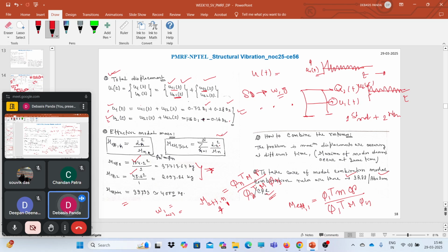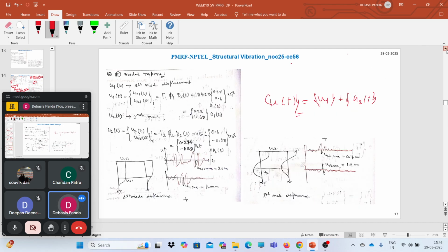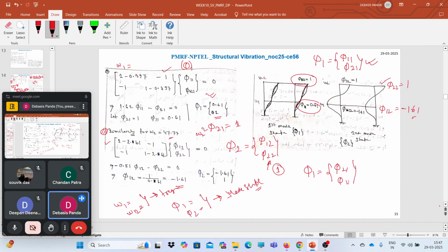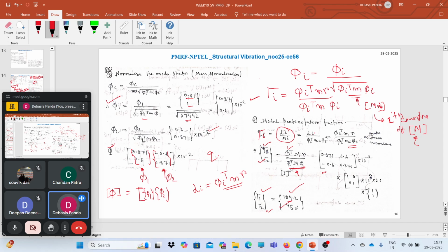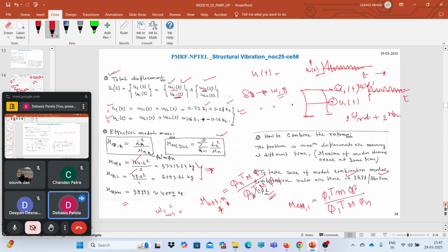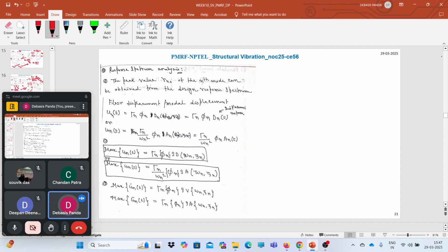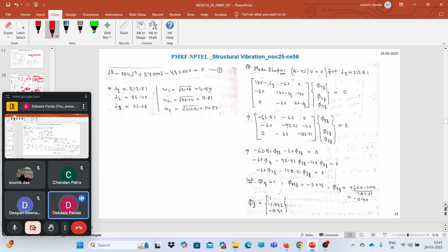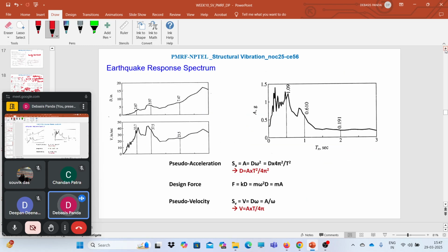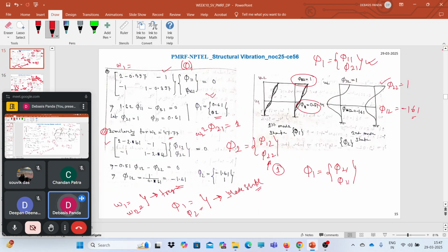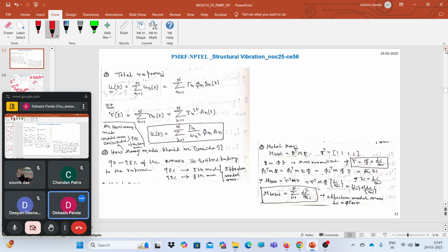So that's why that Ln we have abbreviated earlier actually gives us information about the modal mass, because when we consider the responses, first we need to consider that modal mass, or the 90% of the modal mass. We need to consider the modes up to that 90% of the modal mass.